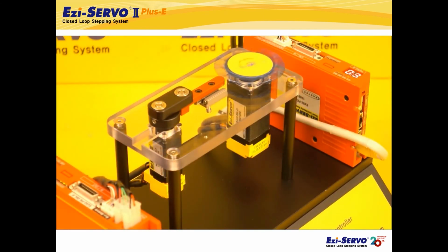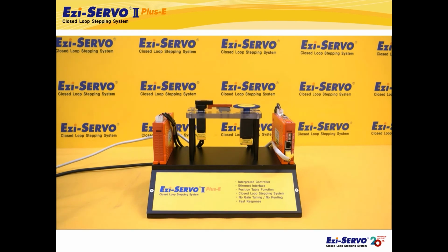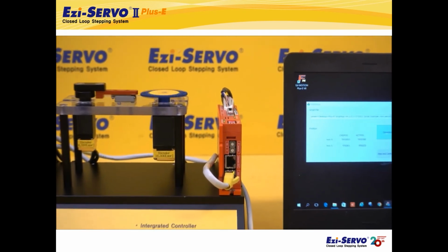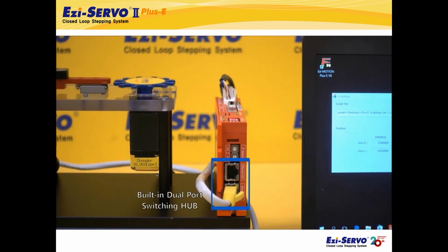Because it is a closed-loop stepping system, precise position control is possible through a high-resolution encoder, and it is optimal for such high-speed, short-pitch motion because of the characteristic of a stepping motor without hunting after stopping. In addition, by directly connecting Ezi-SERVO Plus-E to a PC through the Ethernet port, it is possible to simply control it with the API provided by FASTECH.